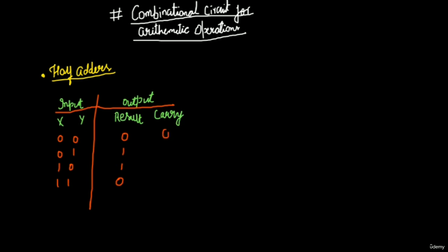Well, it will not be contradictory anymore when I write the carry. This one is going to give us 0 carry, this one is going to give us 0 carry, 0, but this one is going to give us the carry 1, and that's the game-changing thing. And then the 0 and 1 together give us the result finally that we get 1. So this is something that we need to understand: carry is something, 1 plus 1 is actually 0, or you can say it's just the place value that changed. So the place value became 0, but the 1 came as a carry. So together we are going to write the 1.